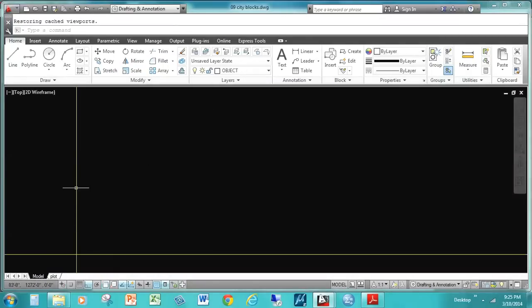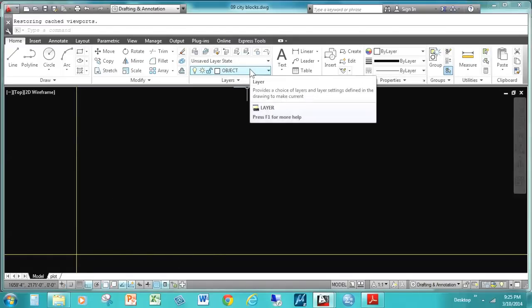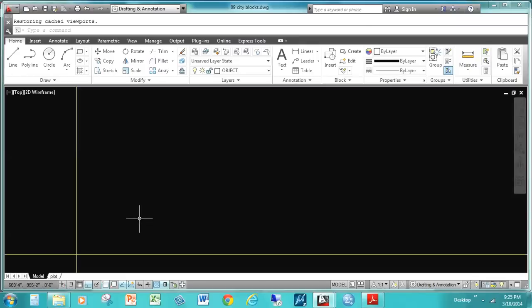Right now we have 2 construction lines. We're going to use these for the start point. Once we start, we're going to get rid of them. So the object layer should be selected, and then we are going to start drawing a line. So L, enter, and here's my command line. We can follow the lines and the steps. So L, enter, specify first point. We're going to left click here.